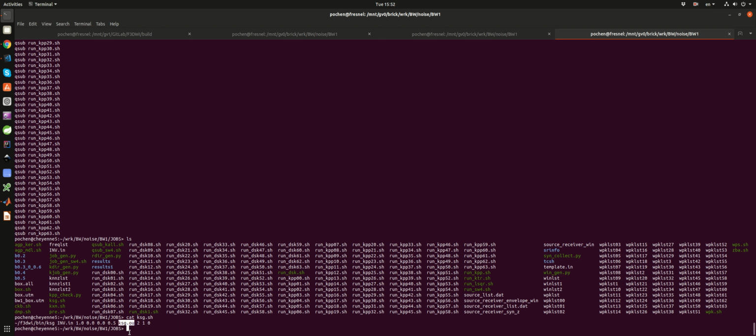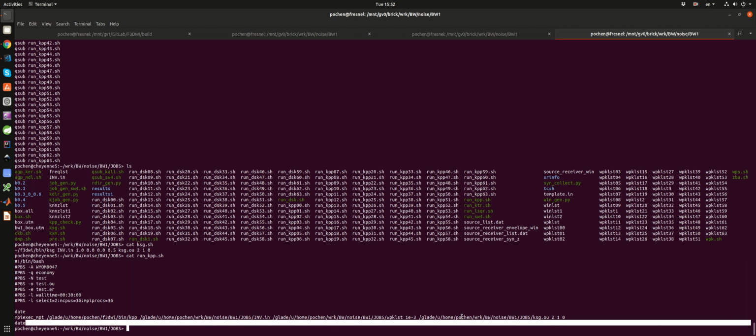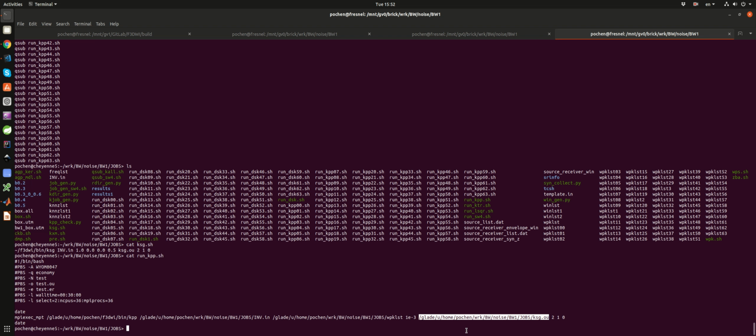And then the output file is going to be written into this particular binary, and then we have this permutation 210, right? So this particular output file ksg.out is going to be used in the KPP, in the post-processing. That's this command line input. This command line input can be this particular scaling file, or it can be just a constant. If you put something like 1.0 here, then there's no scaling at all. The kernel is going to be used as is. It's not going to do any kind of scaling.